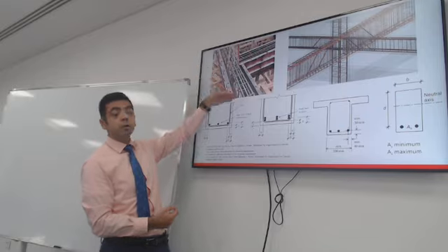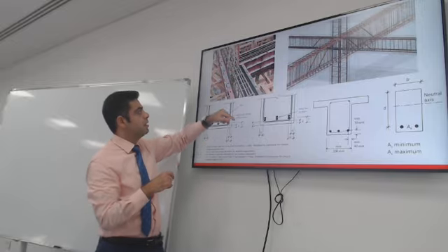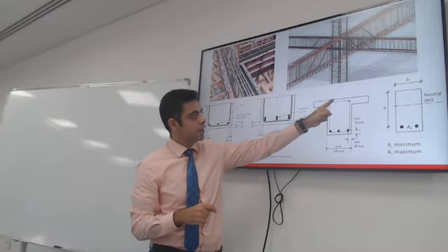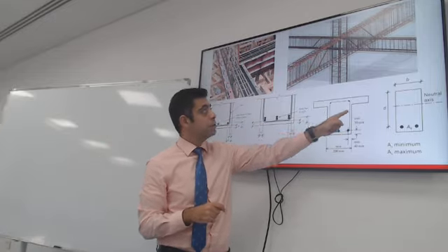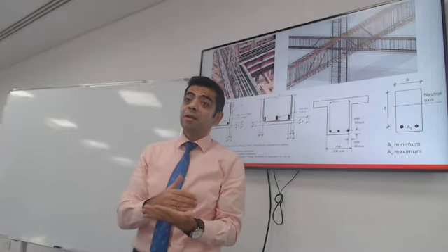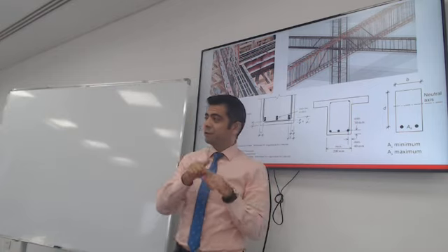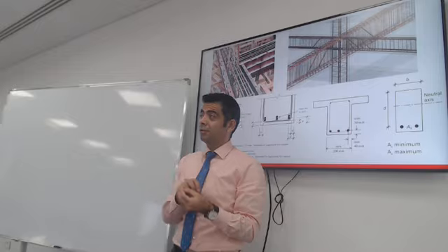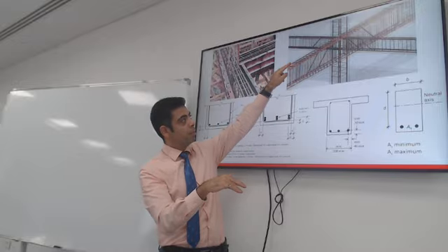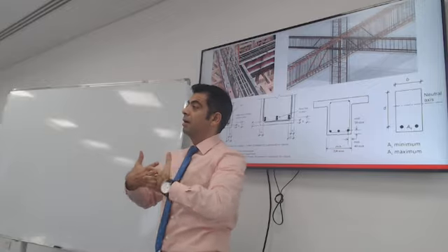And you have vertical reinforcement, or ties, or links, or stirrups. The Eurocode will call them links or stirrups. These are these double lines. Do you see this kind of enclosed line? This represents the vertical links, which we are going to be talking about next lecture when we design a beam for shear. The vertical links, the vertical stirrups, will resist shear. The horizontal bars, the top layer or the very bottom layer, will resist the bending moment on the beam.